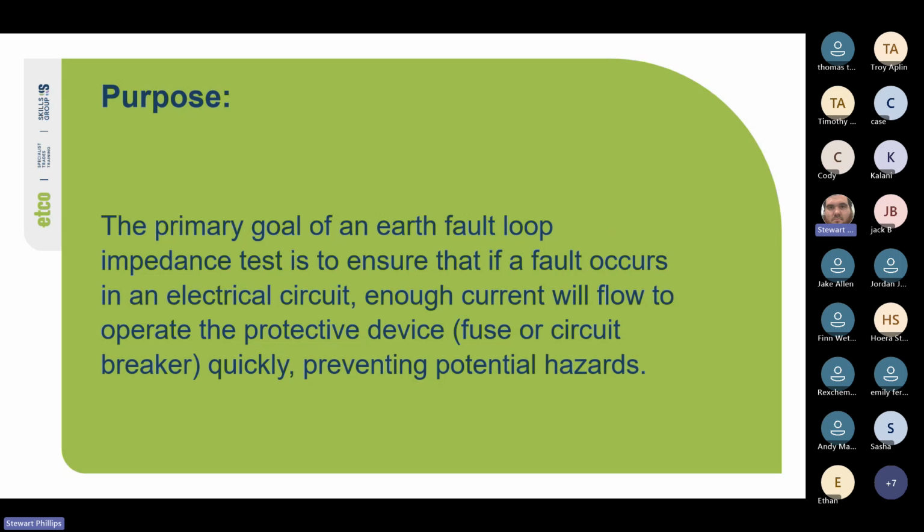I've had a couple of jobs where you go to the client's house because they're complaining they don't have power, and you measure the voltage at the switchboard, and you've got 120 volts. Oops. So in that case, you call Wellington Electricity for us in Wellington, or at least it was until recently, and they're like, "Oh yeah, we're fixing it. Yeah, we know the transformer's buggered. We'll be there soon." It happens.